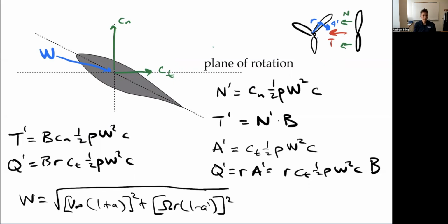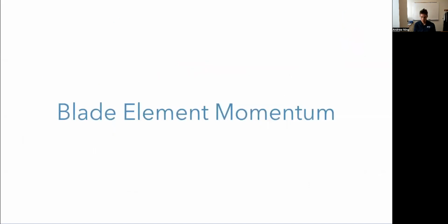Okay, great. So as said, we now have these two pieces. We got thrust and torque from momentum theory, thrust and torque from blade element theory. We can now equate them to get our blade element momentum theory. All right, so let's just do that. Thrust, okay? And both were thrust per unit length. We just did that one per unit length, but remember before we did the momentum for this little annulus, so it was per unit length as well.